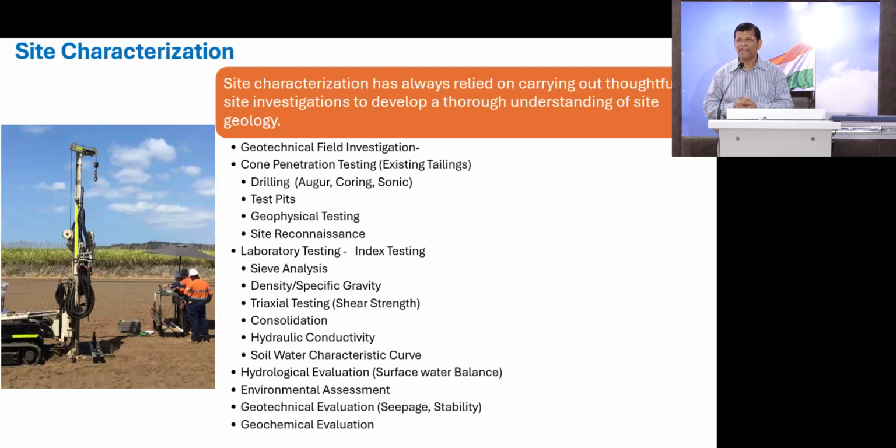And it is considered an undisturbed sample? It is considered an undisturbed sample, but the main thing is you may not get the same as with a Shelby tube for clay soil. Exactly. But you can stop it and take the sample if you want. So it's undisturbed, you can do that.